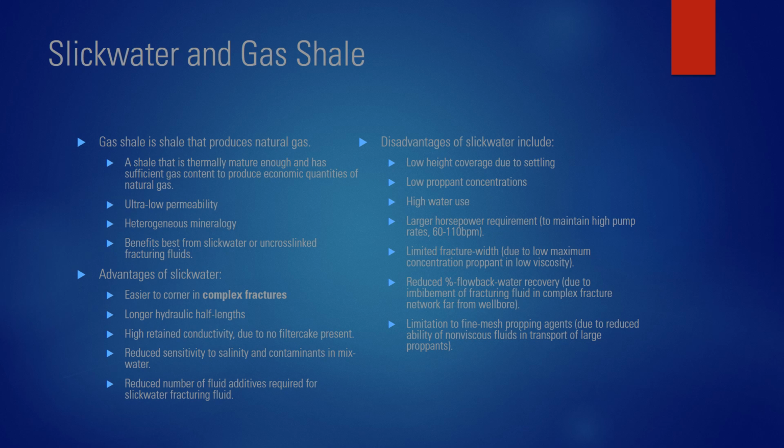It has reduced percent flowback water recovery due to imbibement of fracturing fluid in the complex fracture network far from the wellbore. It's limited to fine mesh propping agents due to the reduced ability of non-viscous fluids to transport large proppants.